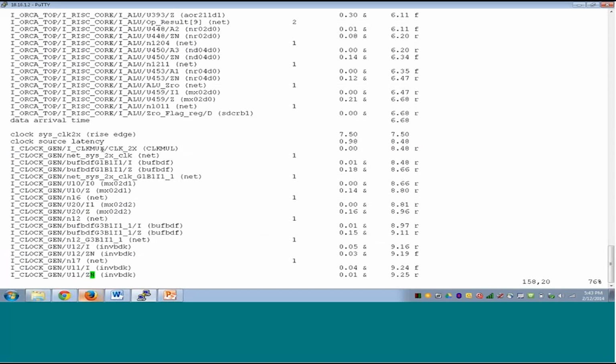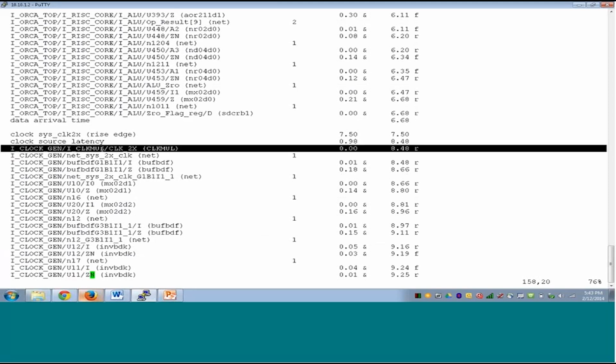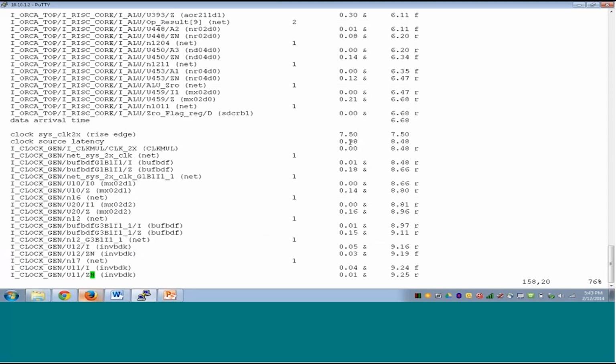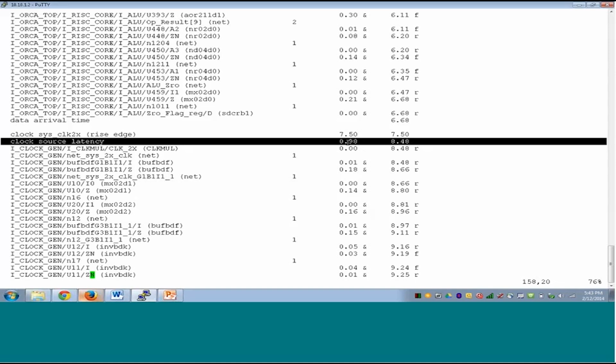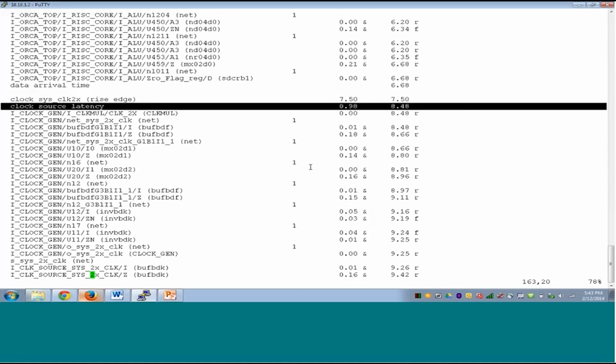But it starts at the generated clock creation point, which is this. If this generated clock latency is 0, then there is something wrong. If you have defined a generated clock and there is clock generation logic, it should be timed correctly. Then only it's correct. If the figure here is 0, there is something wrong, and obviously you will get some check timing messages. You will also get messages during update timing. But we did not get any messages, and we have some figure here, right? So it's correct. And then we also see the clock capture path as well.